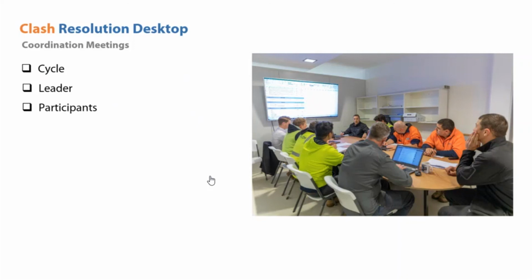Participants are basically the BIM coordinator, technicians or discipline model managers, and professional designers who need to be involved. These are the recommended participants for a clash meeting. The preparation for the coordination meeting shall be done by the BIM coordinator for the project. It usually consists of ensuring the publication of clash reports prior to the meeting. It is recommended to have these reports ready 2 days prior so that the receivers get enough time to review the highlighted clashes on their own, and preparing a hard or electronic copy of the clash report to be given to each stakeholder prior to the meeting.